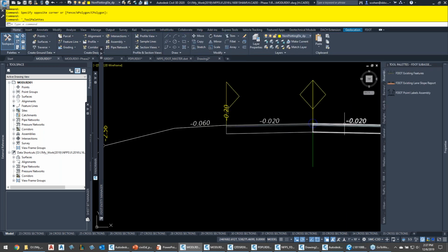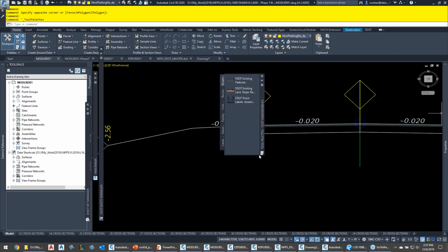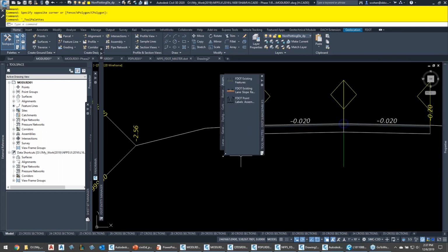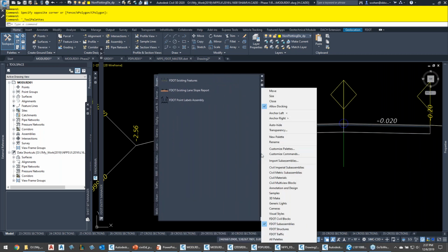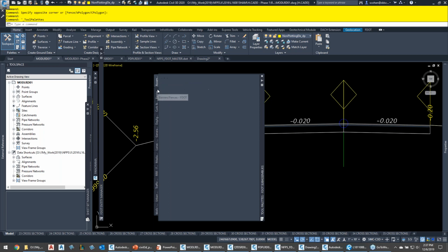If you're not familiar, if you install the DOT State Kit, which you have to do, what you'll see is in your tool palettes, you should be somewhat familiar with how to get the sub assemblies in the tool palettes here, okay? But what the DOT installs when you install the State Kit is their sub-assemblies, and they have their own palette group called FDOT Sub Assemblies. And if you go through the different categories, different palettes, you will find all the different sub-assemblies unique to doing DOT projects, right?